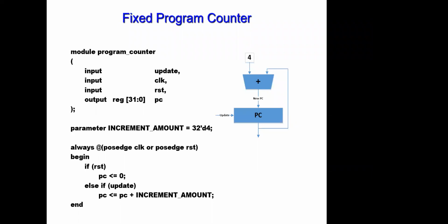But before that, let's say that we would like to write that particular step in Verilog. How can we do that? I will have my program counter, and each time the program counter will be updated to program counter + 4. How do I write a simple Verilog code for something like that? I have to define, of course, all my inputs and outputs. This one will be updating the program counter each time. I have to have an input called clock and an input called reset. This is always the case with any sequential machine, correct? I have to have a clock and a reset. If I would like to reset all of my data, I have to have a button such that when I hit reset, everything will be 0.